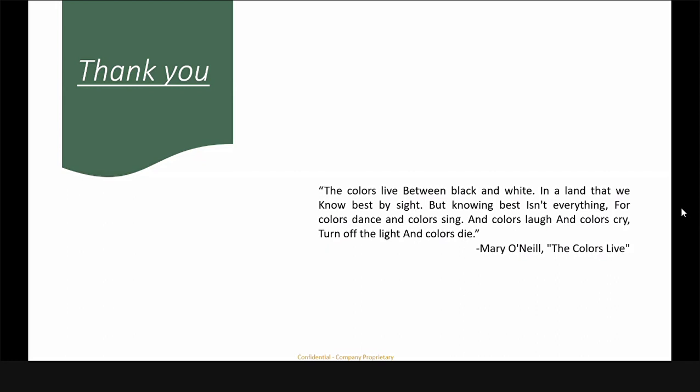And in our X-Rite system, we have a color value. It is common whether it is reflectance or transmission. When it is reflectance, the output will be as per K/S. If the measured sample is in transmission mode, then the output will be as per the ABS value. And the color value SWL is equivalent to the ABS SWL.